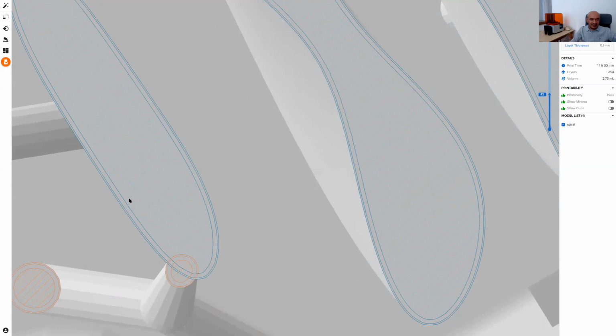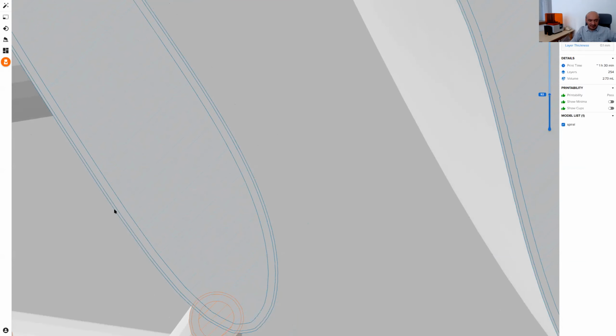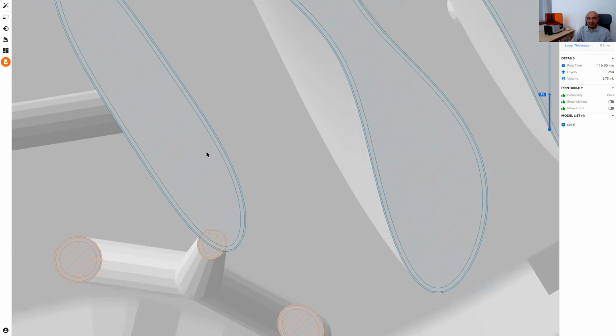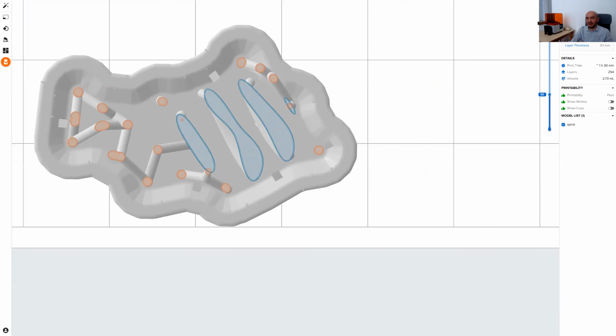And if you look at the details of this contour, what our laser is doing is that it has 3 shells. As you see here, 2 of these shells have very little gap between, and the other one has a bit more gap between the other shells. But once again, we need to fill the interior completely with material. The parts you are building with SLA or other photopolymerization based processes, we should always have solids. We cannot have voids inside. We cannot have different infill patterns. They should always be completely filled.